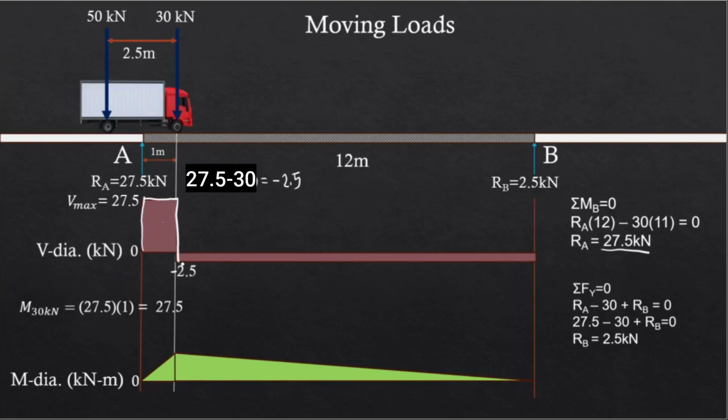So that's going to be a straight line. Just follow this one. Now for the moment diagram, again, this is a positive constant line. And so we have here an ascending line, which is 1 degree. Because again, we have 0 degrees right here, plus 1 for the moment diagram. That's going to be 1 degree. And also right here, this is 0 degrees, and this is 1 degree.